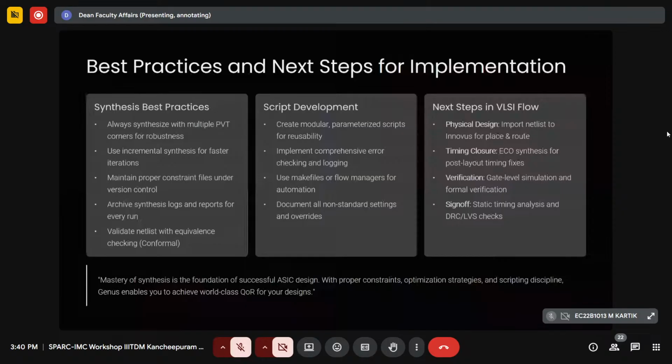If it is part of digital code, it cannot synthesize. That's what I said about the constructs, I talked about the constructs initially. Only synthesizable constructs need to be used in the RTL. If not, it cannot synthesize. The tool doesn't have the capability to synthesize memory. So we need to separate that memory as a separate module. A memory module can be there, but it can be referenced through a library itself.